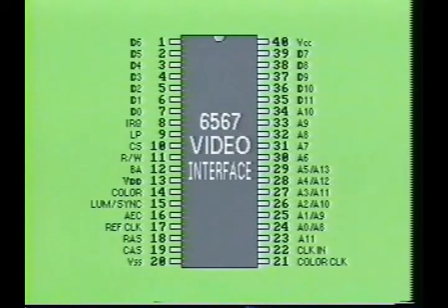Here you see a very popular video interface integrated circuit. This IC chip contains its own type of support latches and registers previously described. However, this device uses an 8x8 or 12x8 character font and is capable of generating a color screen as well as support circuitry for refreshing dynamic RAM chips and CPU clock timing. This input-output device transforms digital signals into complex video waveforms used by composite-type monitors.